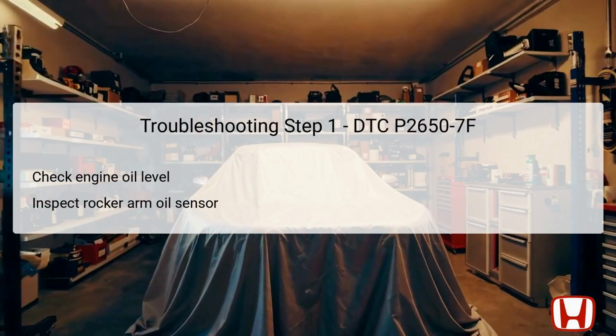The first step in troubleshooting DTC P2650-7F involves checking the engine oil level. Insufficient oil can lead to low pressure readings, which would trigger the DTC. Hence, verifying that the oil level meets the manufacturer's specifications is essential before proceeding to more complex diagnostics.